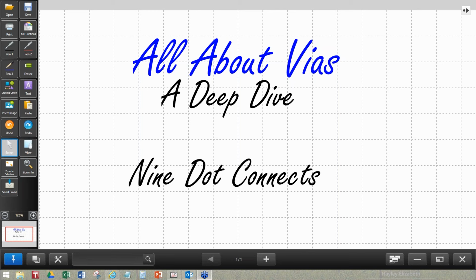If instead I come along and say, what happens if I fill the inside of that sphere with some high dielectric material? Will that affect its capacitance to the outside world? Well, the answer is no, because there's no electric field inside the sphere. All of the effects that are going on with capacitance between that sphere and the other things around it are on the outside. So the answer would be no.